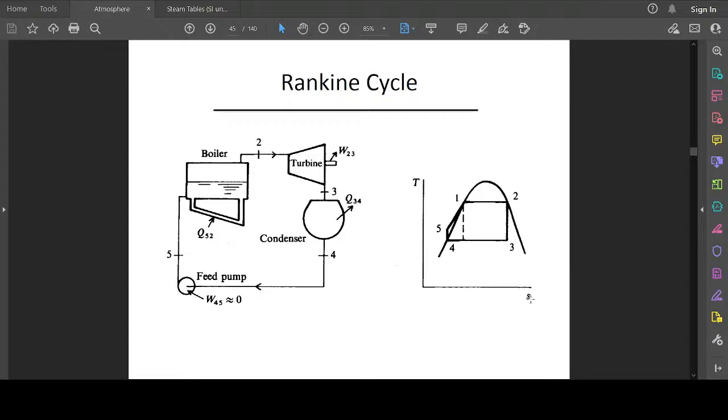So the usual thing happens within the cycle here, but the change now is that from the boiler we get the saturated vapor, which goes into the turbine and does work. From point 3, the condensation stage, all the liquid-vapor mixture is condensed to liquid and fed to a pump, and is brought to the boiler pressure, and that is heated up as well.